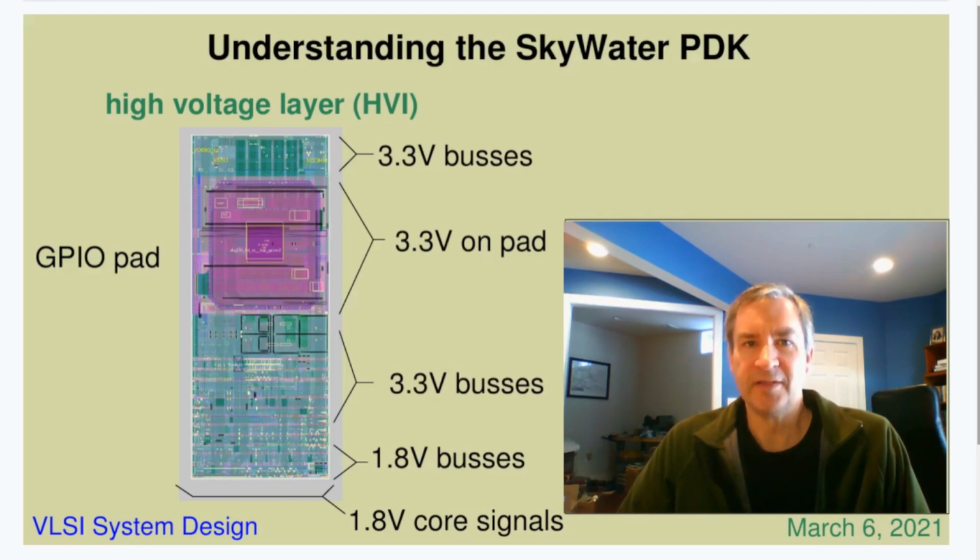The pad frame cells in the SkyWater I/O library reflect this dual domain design methodology with a typical core voltage of 1.8 volts and a pad voltage of 3.3 volts.